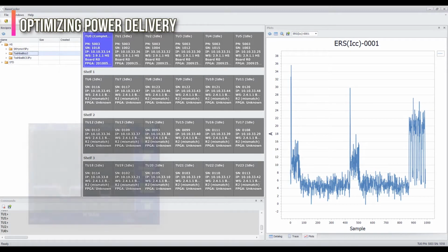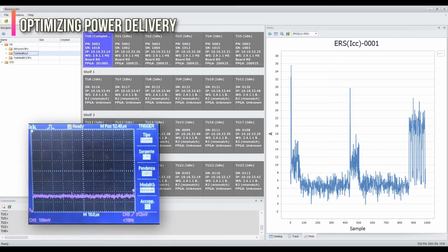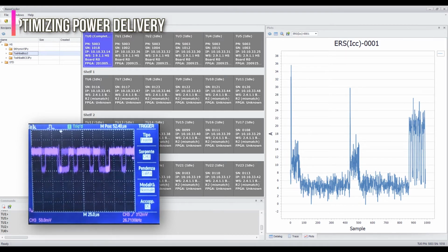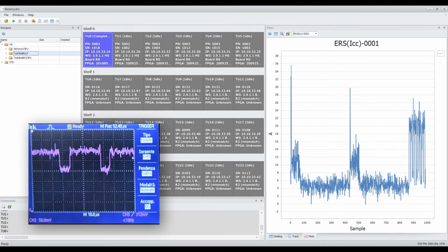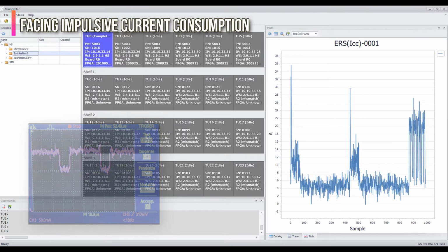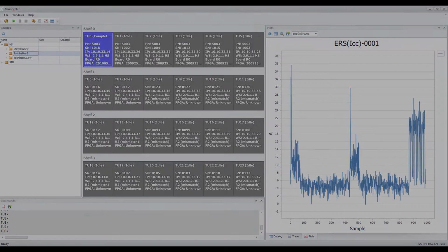Crashes and other hard-to-explain behaviors are often caused by the incorrect powering subsystem of the SSD. It is economically not reasonable to design this subsystem for the worst case indicated by the NAND datasheet. As NAND power consumption is very variable during the read-write-erase operations, a good filtering system and correct layout is needed to provide good quality supplies.